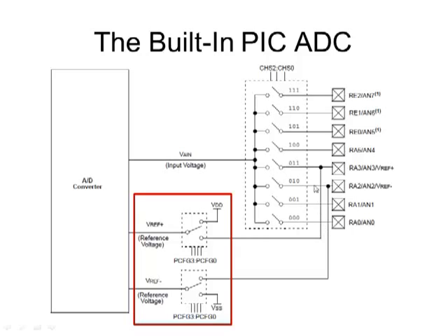I can use, let's see, going up here, VREF plus, that's an external pin that has multiple purposes here, but I can use that pin as a reference, my plus and minus references there, okay, or I can use some combination of those things. And my port configuration bits will define which of those we're using. I'll get more into the detail on those bits in a couple of minutes.